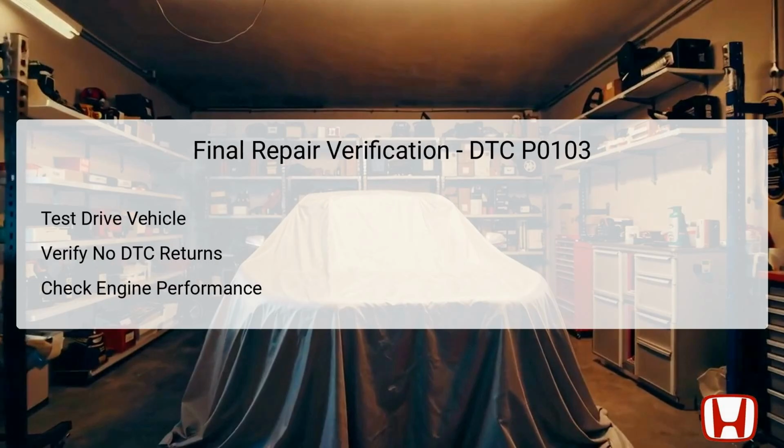After completing all necessary repairs recommended for DTC P0103, conducting a final verification is critical to ensure that the issue has been resolved effectively. Begin by performing a test drive of the vehicle in various driving conditions to stress the engine and the newly installed components. Monitor all dashboard indicators, especially the check engine light, to confirm that it remains off during and after the drive.